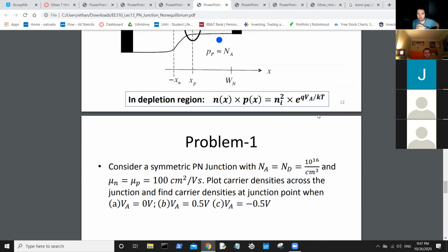What you'd do is set those and leave them be. You would say Nx squared or Px squared, because they're set equal to each other, it doesn't matter, is equal to the number you get on the right side. Then you would square root the number on the right side. That would give you your value of N and P, which you would then plug into your resistivity equation in place of ND and NA. And that will give you your 20 ohm centimeters resistivity.